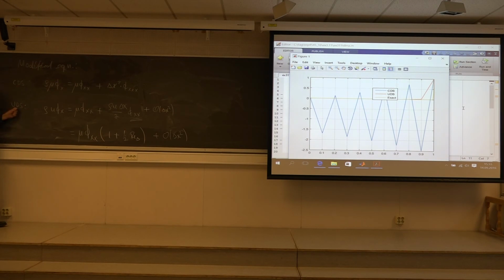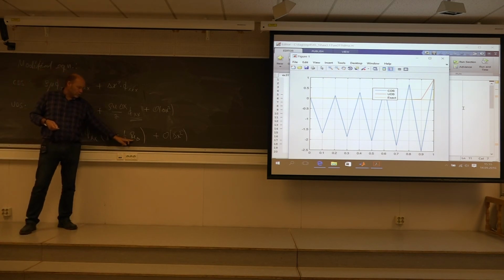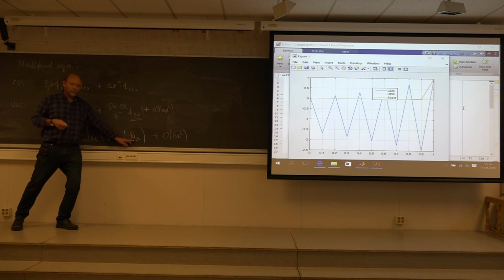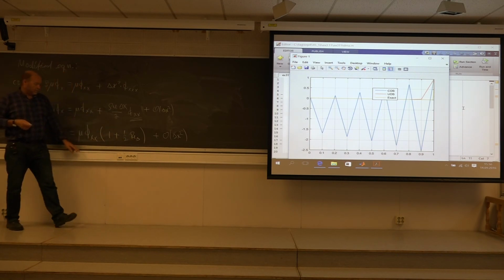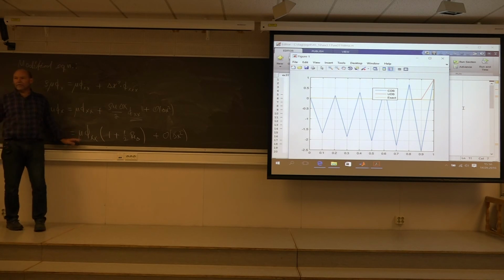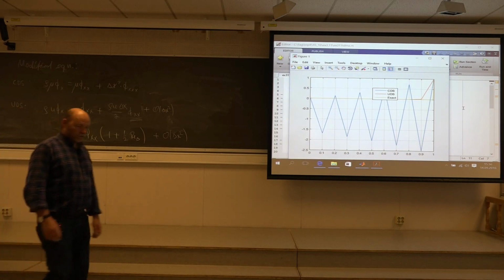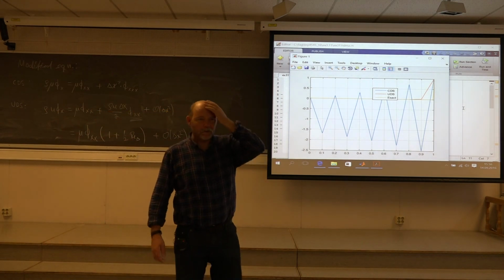The upwind scheme is stable. Yes, that's true. But if the cell Reynolds number is 2, you have actually doubled the viscosity. So you think you are simulating water, but actually you are simulating honey or something very sticky. So that's a surprise for you. Or say if the cell Reynolds number was 10 or 20 or 100, well, then the viscosity is 101 times larger than what it should be. So, of course, using first order upwind schemes, no, it's not a good idea.